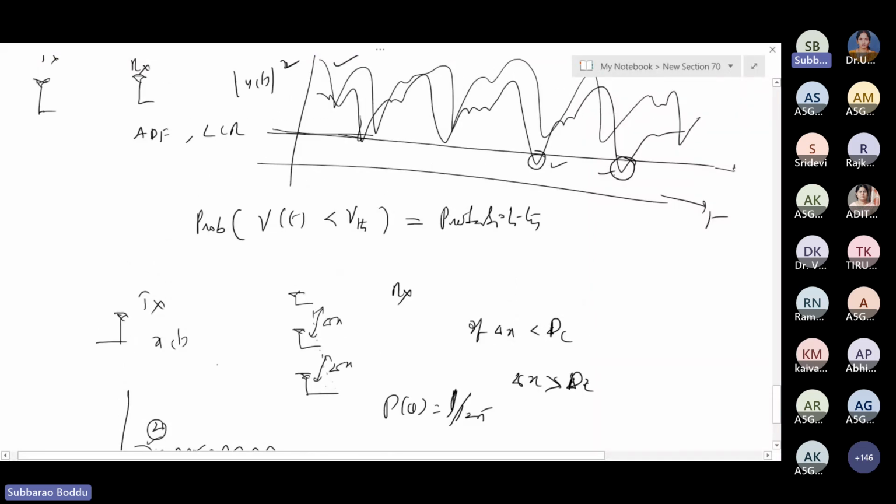I'm wasting the power basically. So instead of that, if you keep many antennas at the receiver side, within several tens of coherence distance within a certain region, here we have not used the entire power, I mean extra power. We have kept the same average power within several tens of coherence distance.